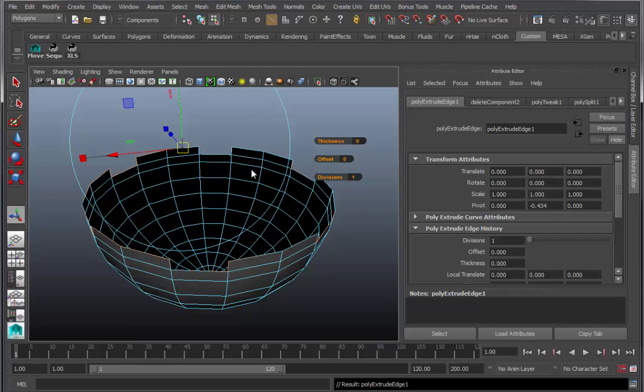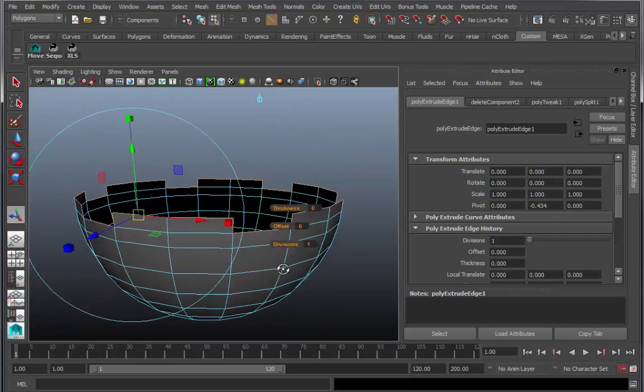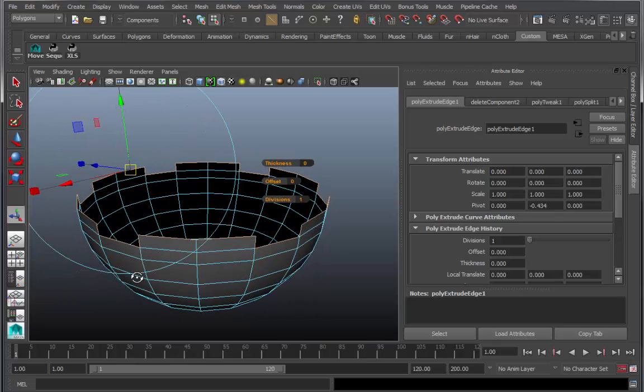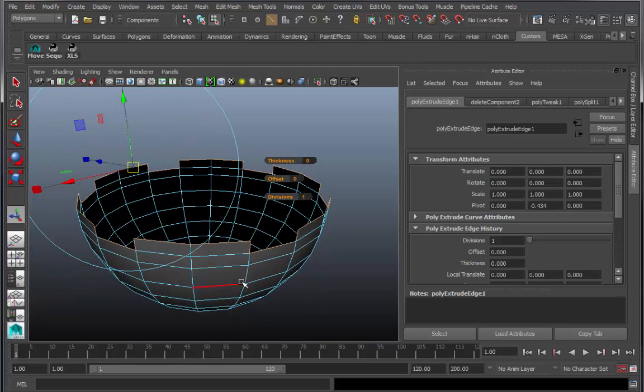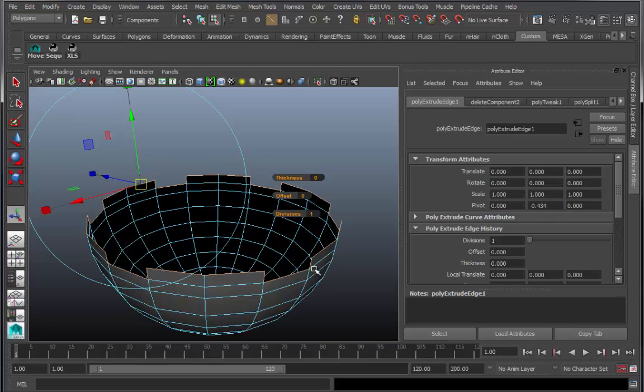If you click on that, now what Maya has done is it said, great, I am currently going to draw a new polygon starting at each of these edges that you've selected. However, because each of these edges points a different direction, there's the slightest rotation between these two, and there's a more dramatic rotation here, it doesn't really know which direction you want it to pull all these edges in.